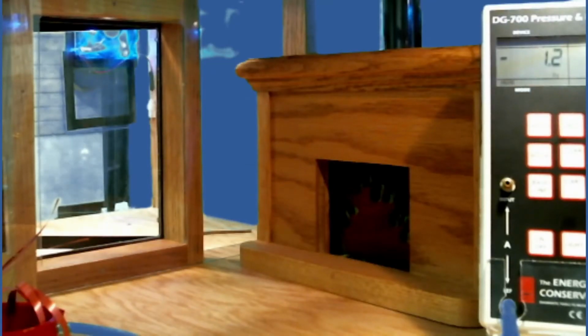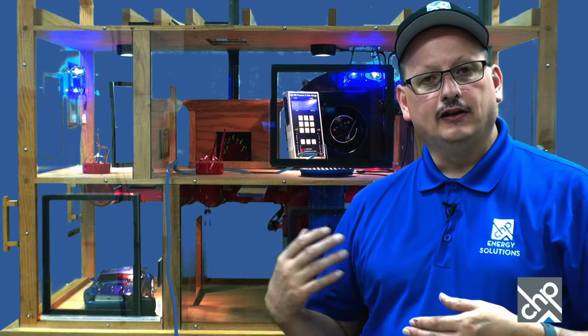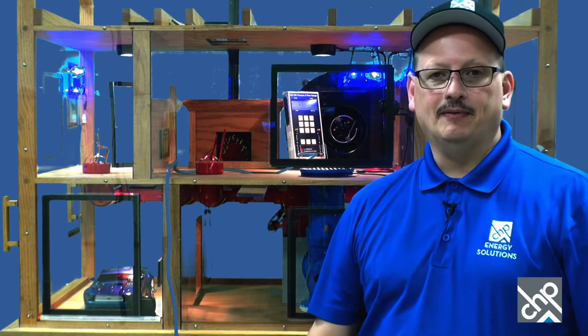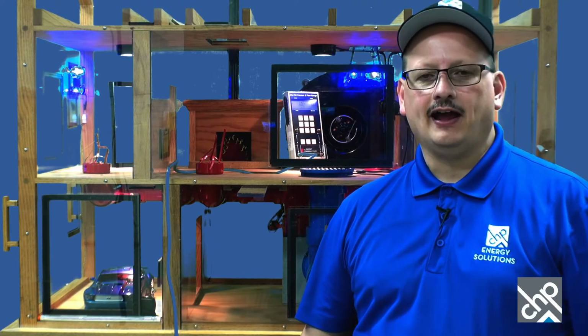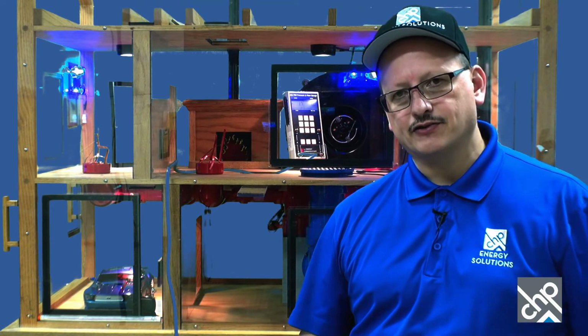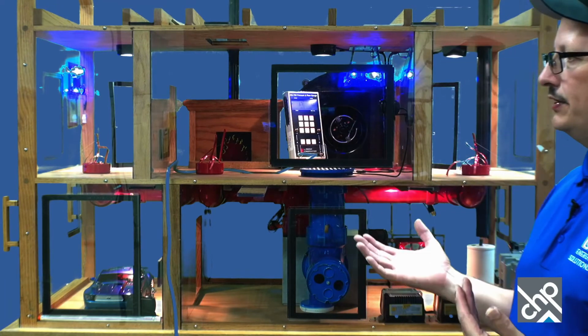So the inside view there, that's with the dryer off, and that's with the dryer on. So even though the dryer's in the basement, it's still affecting the pressure upstairs. And of course, that depends on the tightness of the house. If it's a really leaky house, it might not have made much difference. But the tighter the house, even though a fan might be across the building, it might still make some pressure differences. Okay? Quite often it will. So that's each one of those fans on.